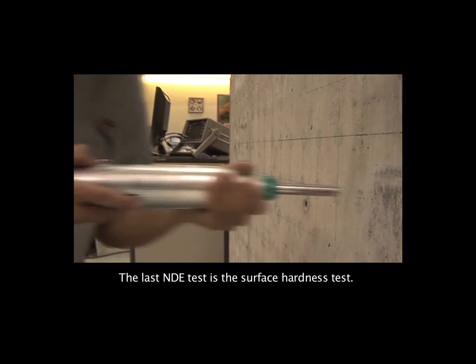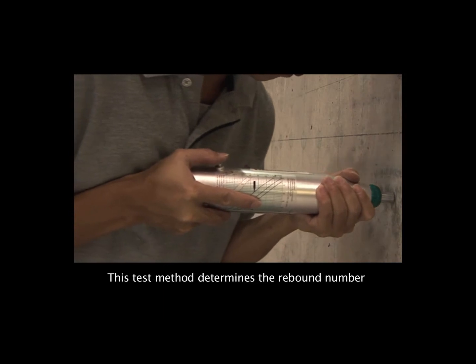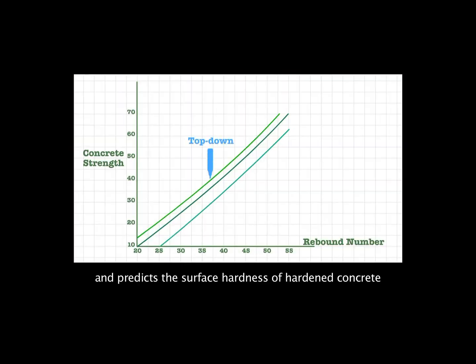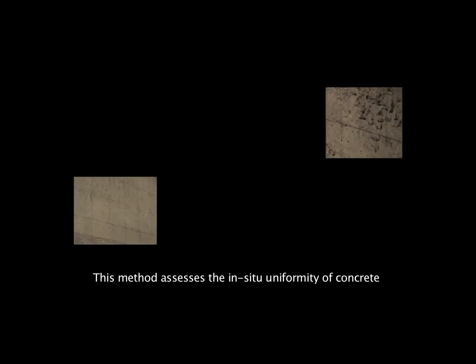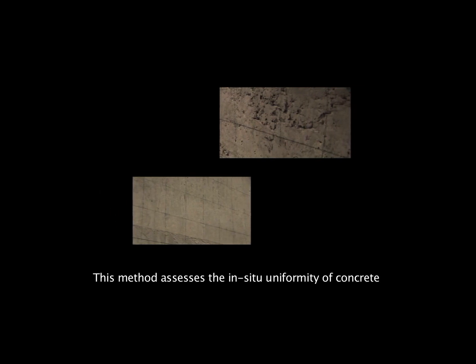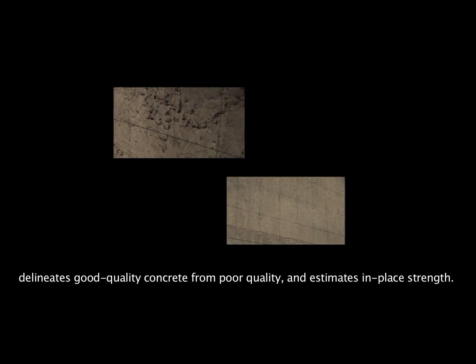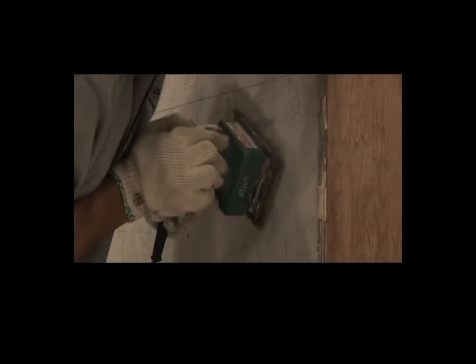The last NDE test is the surface hardness test. This test method determines the rebound number and predicts the surface hardness of hardened concrete by a spring-driven rebound hammer. This method assesses the in situ uniformity of concrete, delineates good quality concrete from poor quality, and estimates in-place strength.